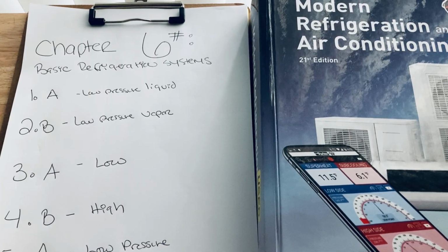All right, so now we're on the critical thinking. Number 1, which state of refrigerant is capable of absorbing the most amount of heat among the following 4 options: high pressure liquid, high pressure vapor, low pressure liquid, low pressure vapor. Select the correct answer and explain why refrigerant in that state can absorb the most amount in BTUs. This is on page 86. The answer is low pressure liquid, and the reference is the dry sponge.